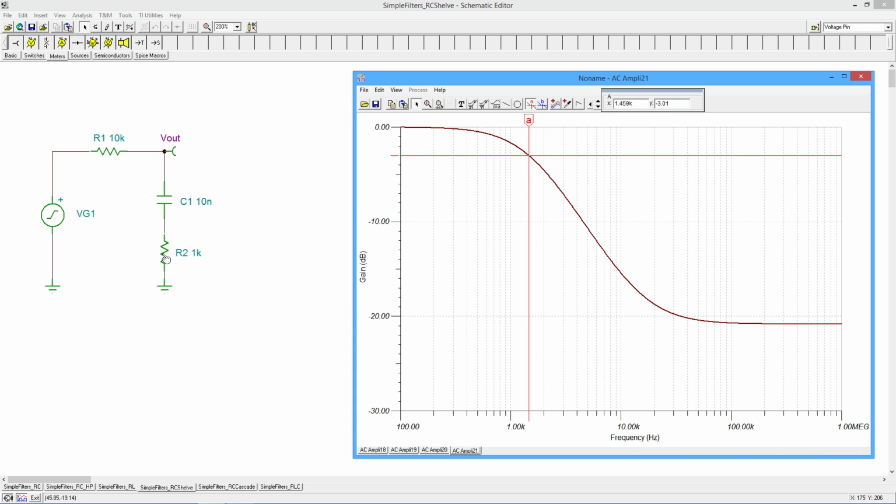Okay, so you can play with this with the value of R2. If you bring R2 smaller, you brought it down to 500 ohms, 100 ohms, whatever, then this curve would continue out farther along before it flattens out again. Okay? And where it curves, that critical frequency is basically controlled by these two values, this cap and this resistor.